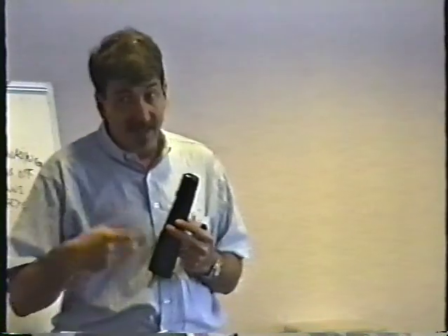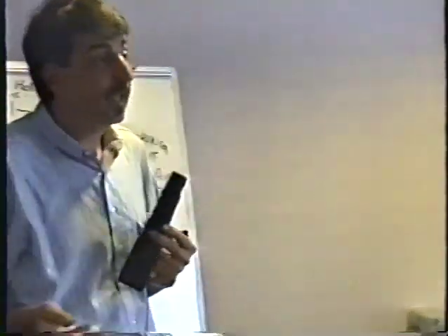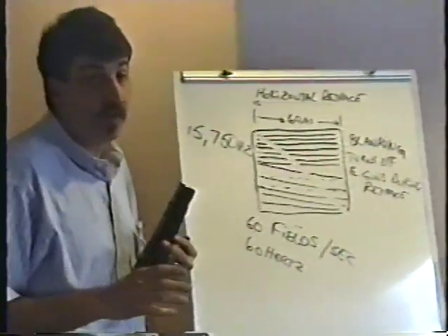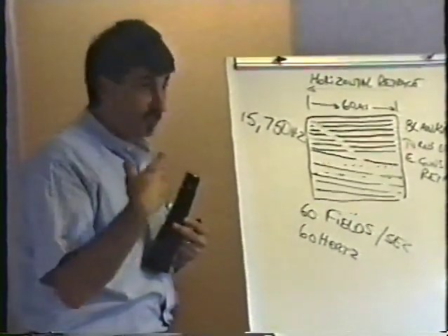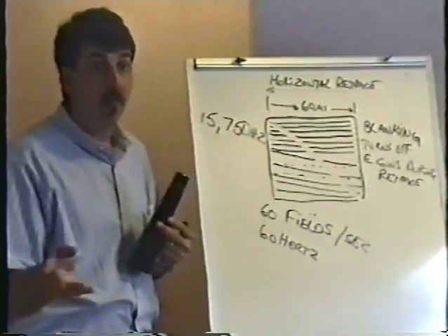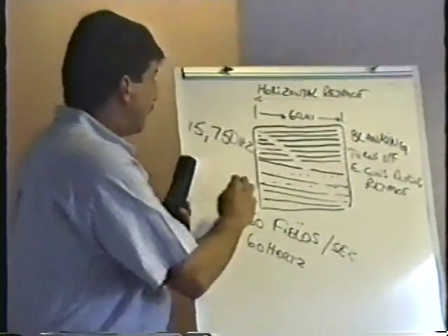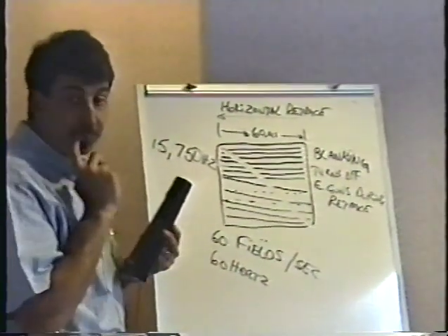As soon as I hear that squeal, I know that the horizontal deflection circuit is working okay, because that's what's making that sound. And the power supply is okay as well. We'll talk a lot more about that squeal later on, because it also tells me that something else is working too, something very important. But that's the horizontal frequency.